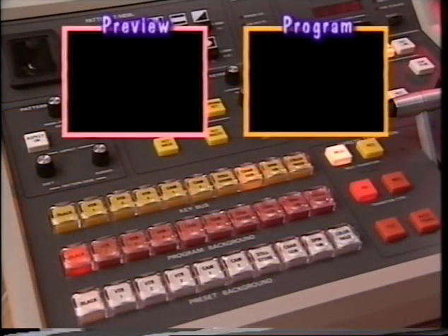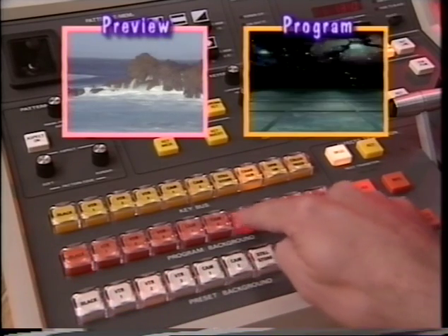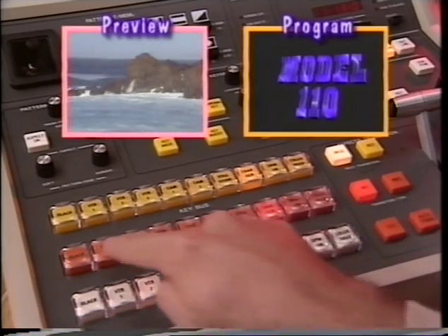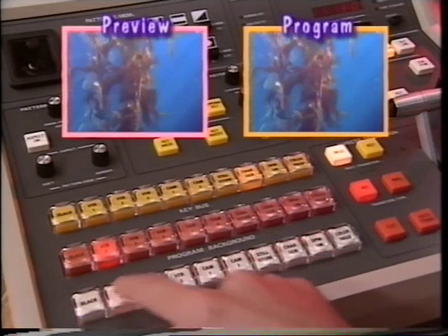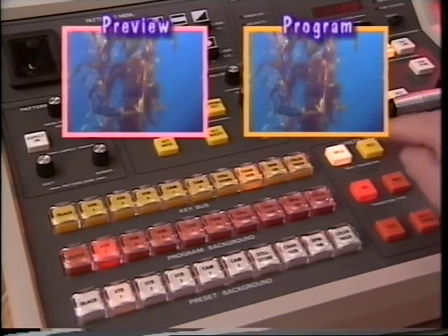The 3 long rows of push buttons at the bottom of the control panel are the primary switcher controls. Pressing a push button on any of the 3 rows, called crosspoint buses, causes the video input signal associated with that push button to be sent to the output of the crosspoint bus.